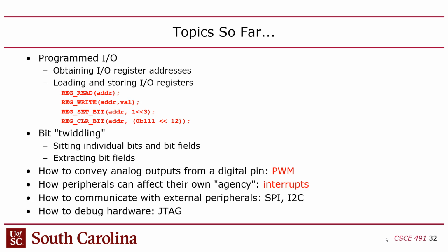So you can use these. These are kind of like helper functions. You can use these, or you can do it with the method I showed you last week as well. Okay, I hope that's clear. So you've got these 4 helper functions, and I call them intrinsics because these 4 functions are mapping to specific assembly instructions. In the case of reg read and reg write, this is a load, that's a store, and these guys are a little bit more complex because they include the extra steps for setting and clearing bits.